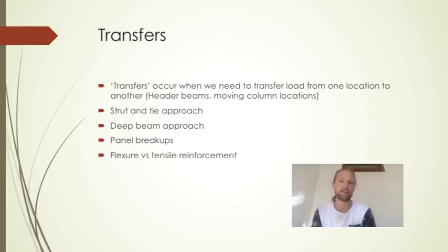So when you design for precast panels, which is starting to become the trend, they are always limited by the crane capacity or the truck capacity. So the panel, you might design it as one big wall, but the panels will be broken up into certain segments. So we'll cover the effect of having panel breakups and how to do them effectively.